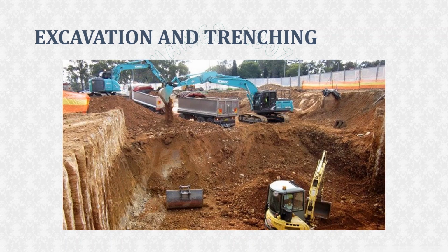The length of a waste pit should be enough to align all dump lines on it. The key factors of waste bed volume are width and depth. We should design a waste pit with enough volume to handle cuttings, dumped mud, and anything you will get rid of. Also, we should accommodate for the rain water. Yes, the rainwater can cause the waste pit to overflow, which has an unpleasant effect on the environment.